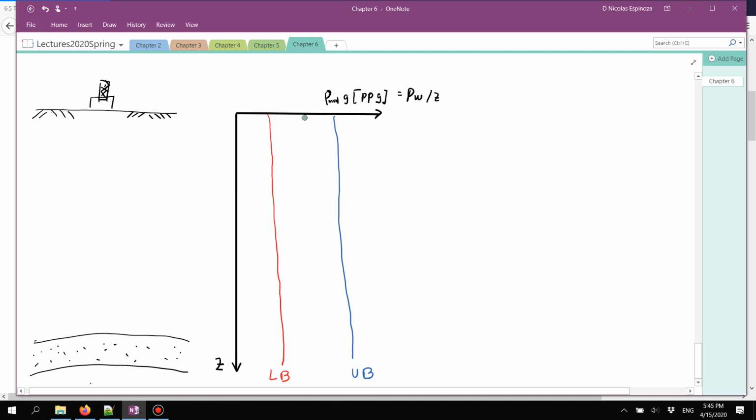And in this case, if you have the same mud circulating all the way through the entire wellbore, let me draw the wellbore first. So let's say that we drill the wellbore and the mud is the same in the entire wellbore, then this is going to be a constant value here, and this is a good solution because it's not too low to hit the lower bound, but it's not too high to hit the upper bound. If that's the case, you could go with just one casing, finish your job and cement your wellbore, and that's the end of the story.